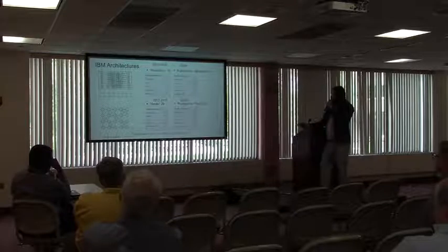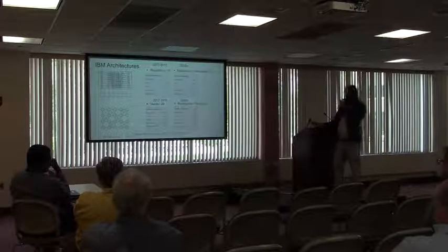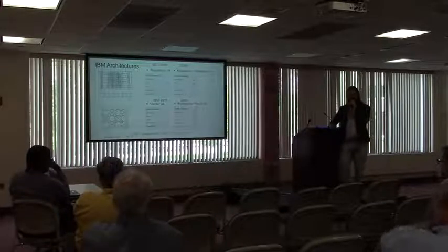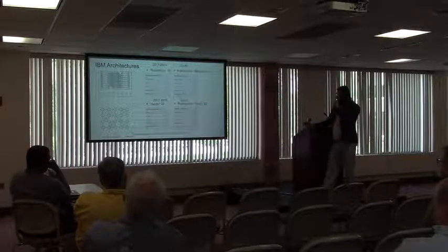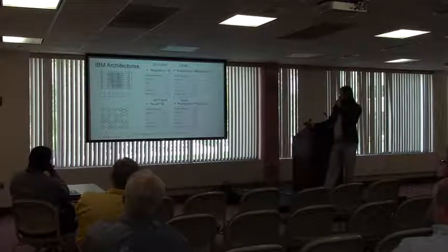And some of the characteristic parameters we discussed are measured for these, and these are measured daily and multiple times a day to make sure that the system is operating within the specified bounds. So, for example, the frequency of this system was above 5 gigahertz, and T1 values were about 44 microseconds, T2 21 microseconds.